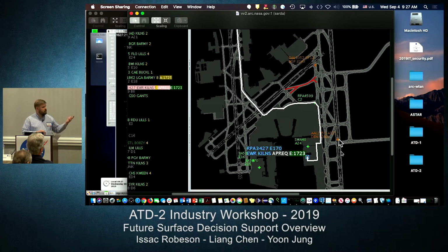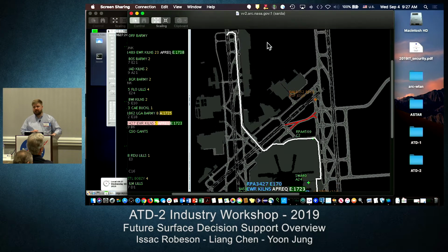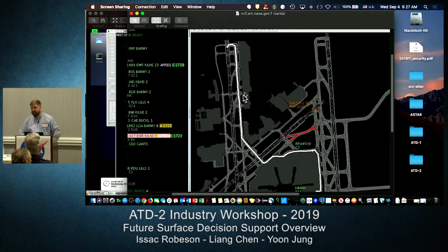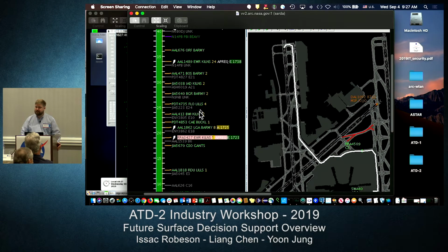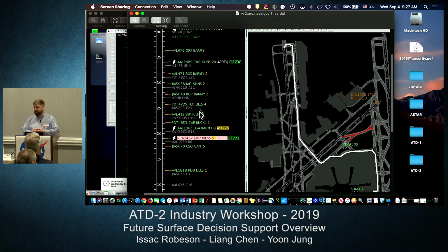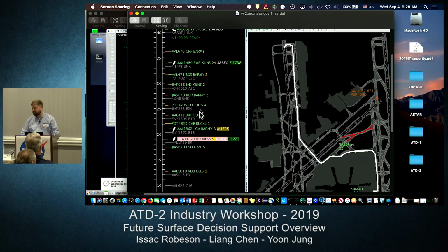At Charlotte, we do detect which flights are part of the miles in trail. We don't update our schedule based on the miles in trail, actually, because there's a lot of uncertainty about the order. We didn't want to be penalizing flights during metering for the runway based on, like, hold this one flight back. In TFDM, there's a separate thing called metering to a miles in trail, if you remember, and just to make sure there's enough of a front loading of that miles in trail restriction so you don't miss gaps. We started kind of simple. We didn't want to jump into too much at Charlotte, so we just said we're not going to separate flights due to miles in trail.